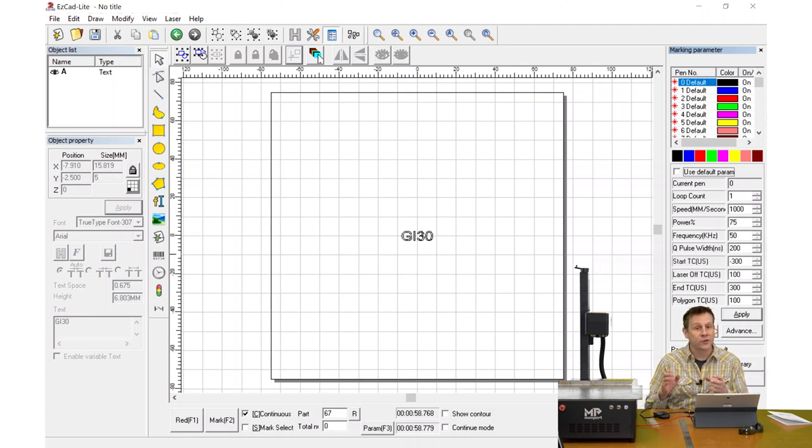and you'll be able to have a better appreciation of how that setting will affect the engraving. Now, with these four different variables for creating engraving, I definitely recommend keeping a log journal book next to your computer and writing down your settings along with the results that you get. If you want to take it one step further as you're learning the effect of different settings of your machine, get a piece of large sheet metal like this, and when you're doing your test engravings, actually type out what your settings are.